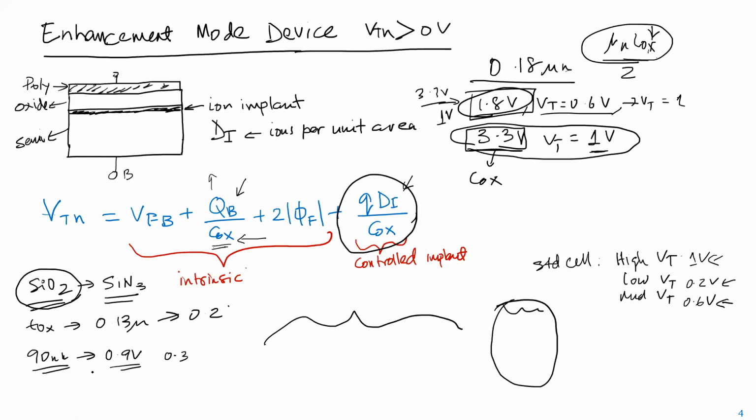But they'll also give me another flavor, the IO devices, which might be 1.8 volt or 3.3 volt devices. These TOXs are larger now, and they are not as fast anymore. They are basically like 0.18 micron technology. So the VTs are different, but they are slower devices, used only for IOs. For high speed, I still have to use the logic devices, where I can't change the TOX. The TOX is still whatever, 60 angstrom or 40 angstrom, whatever that needs to be.